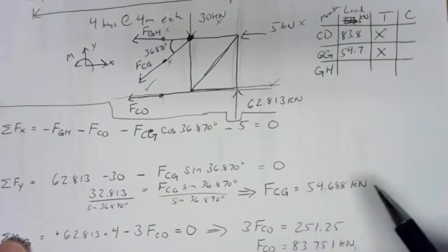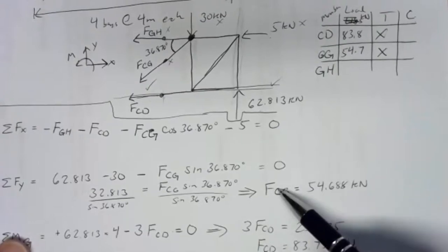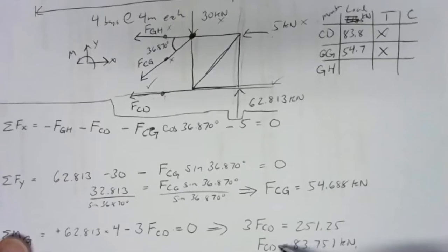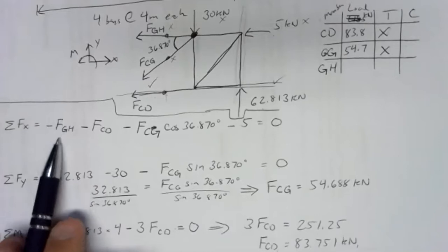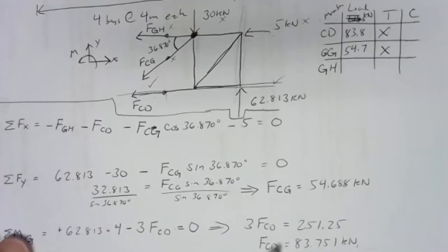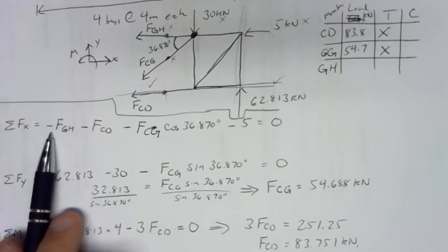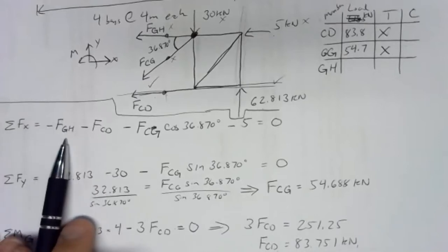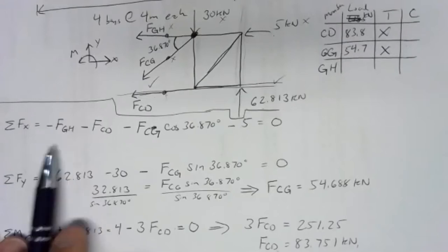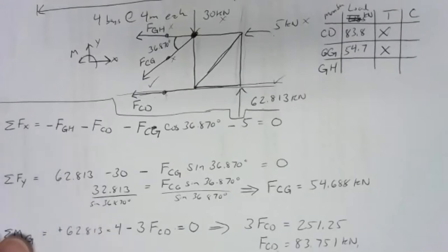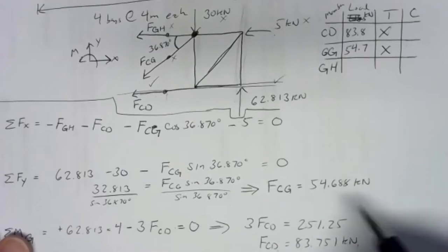And remember that when we go into the x direction equation, or any time we're substituting for one of these unknown values, you have to substitute whatever that numerical value is, including the sign. That can get a little tricky sometimes. If one of these had come out negative, and we've got negative of that value, we'd have two negatives there. That'd be a positive. So you got to work out the signs and such carefully. Fortunately, here these came out positive, so that's not an issue.